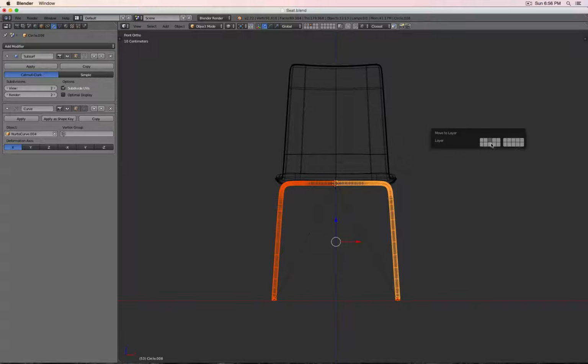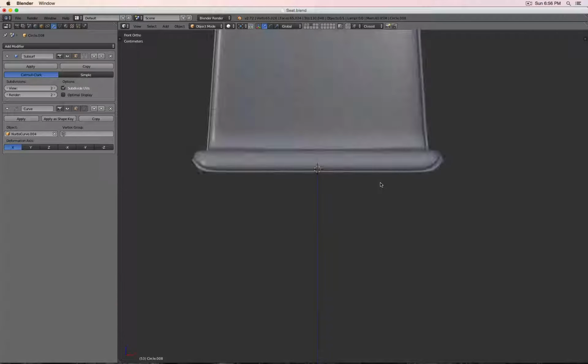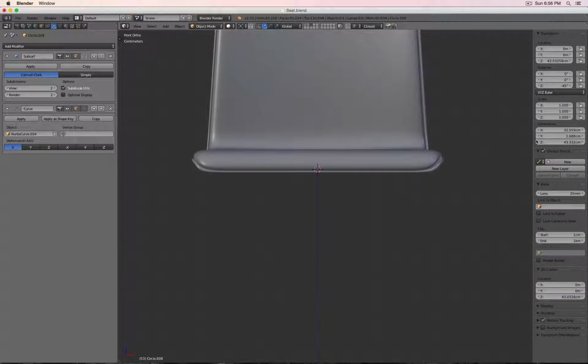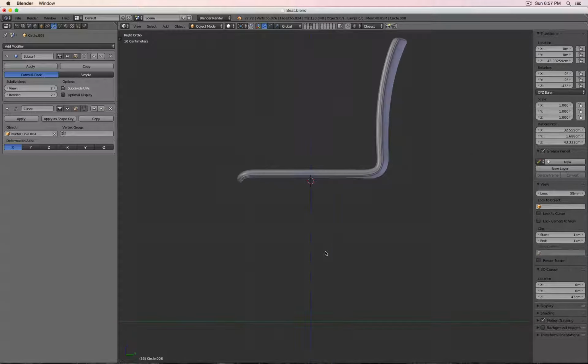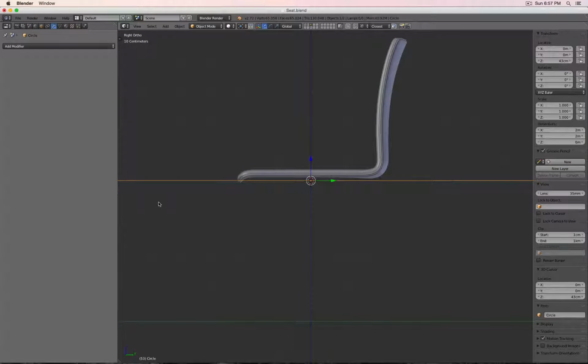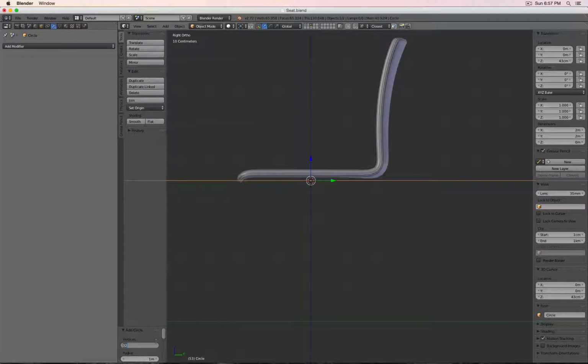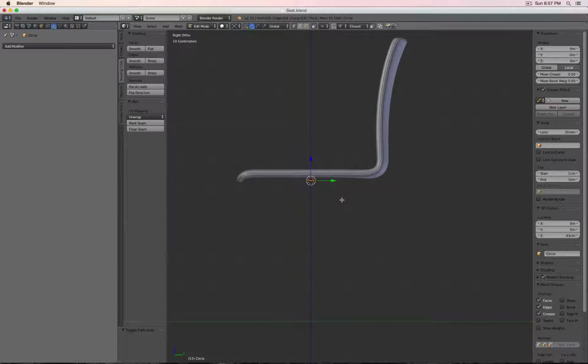So all this, I move on to this layer. So 3D cursor, 4.3 centimeters, X, Y, and Z 0. And I'm creating a small circle, maybe 6 vertices, 1 centimeter radius. So the pipe or the circle has kind of like a 2 centimeter diameter.